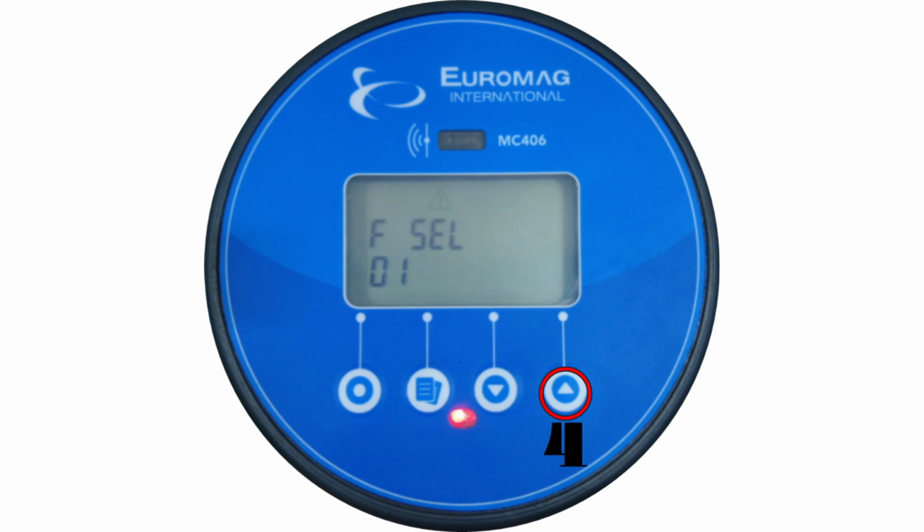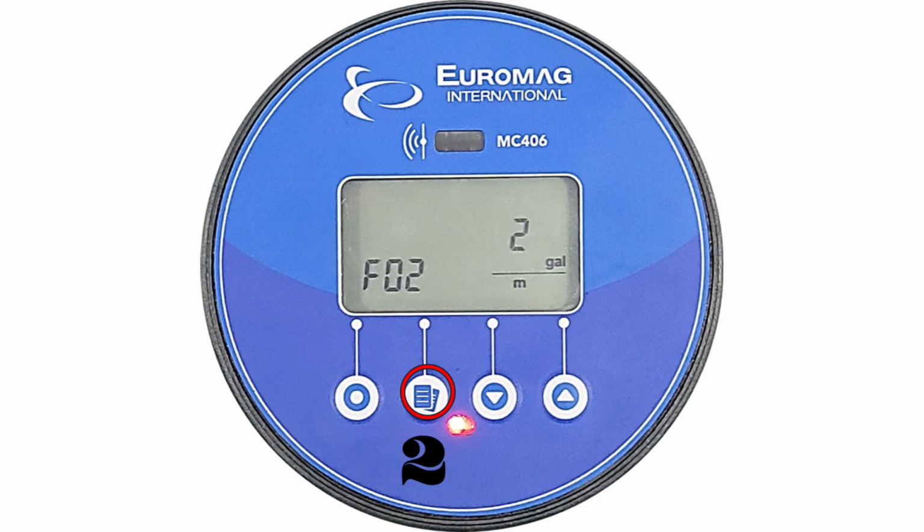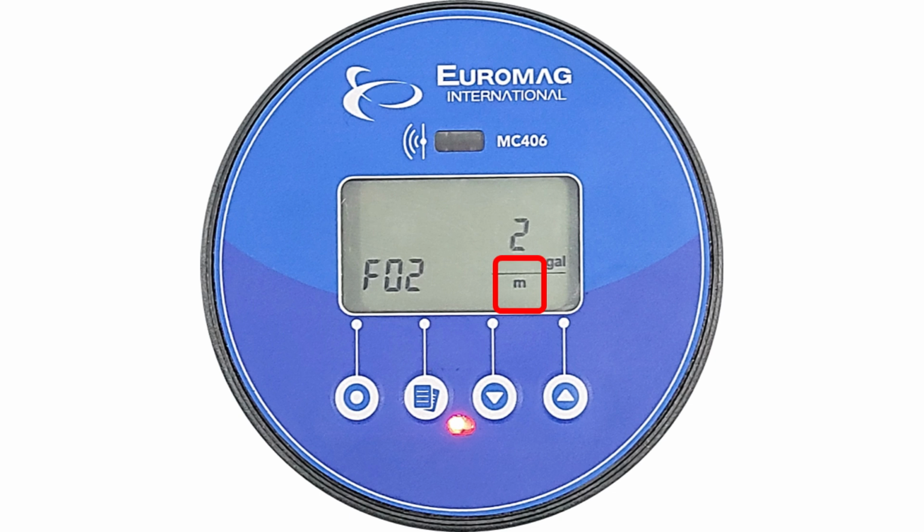Press the number 4 button one time to select function number 2 and the number 2 button to access function number 2. Function number 2 is used to select the time units for the instant flow rate reading. This converter is now showing an instant flow reading in gallons per minute. Press the number 2 button to lock in your changes and return to the function menu.